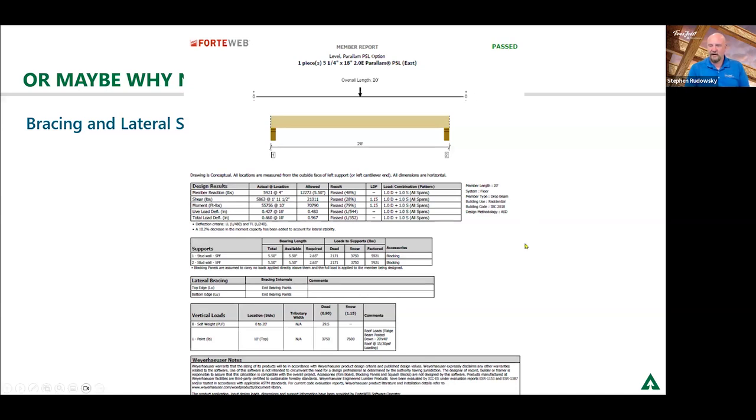So yeah, Ralph put in there that one side loading is also a factor. That's absolutely correct. When you're applying multiple plies together, the strength of the member is really reliant on the transfer of weight, or the transfer of shear, through the connection of the member.